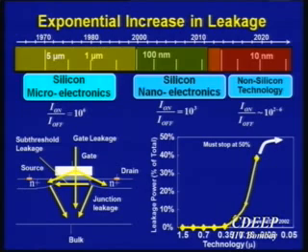Some of you might actually be familiar with drain-induced barrier lowering. Turns out that if you put a drain voltage in your transistor, you actually lower the barrier, right? And due to the lowering of the barrier, your leakage current can increase, and at the same time, you don't have much control. Now, your drain voltage really controls the flow of current through the device, and that's exactly what you don't want, right? So in order to improve DIBL, what people sometimes do is what is called halo doping.